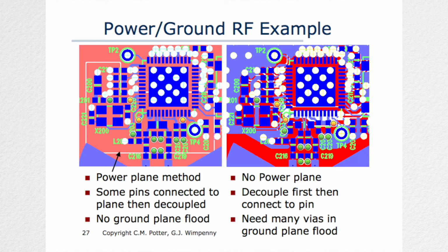And it has a power supply fed into a number of different places. So there is, in particular, RF for the transmit goes into these two pins here. RF for the receive goes into those two pins over there, and RF for the digital goes into those pins over there. And they are separate places on the circuit diagram, and they have been decoupled separately.